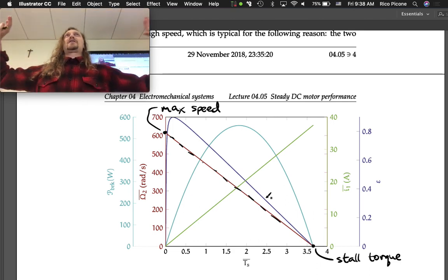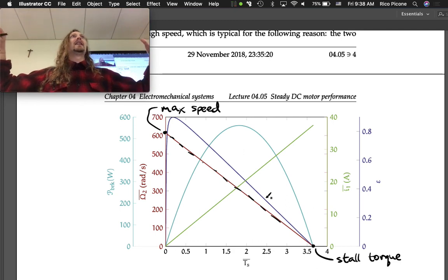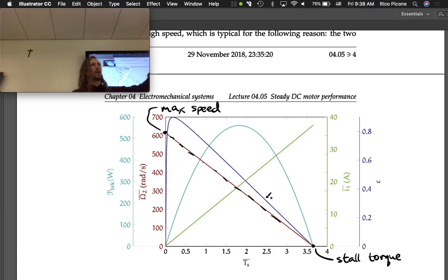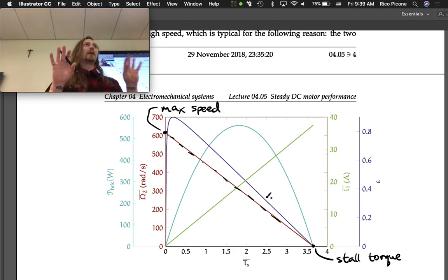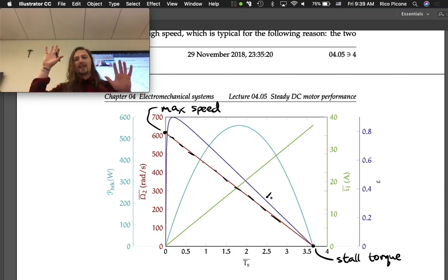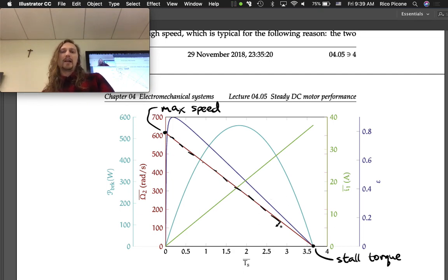So it's not a perfect analogy, but it actually is effectively the same phenomenon, because even in engines you have this torque-speed trade-off. Torque and speed are the two power flow variables and they multiply together to get power, so often your power is what you're trading off between torque and speed. Power doesn't say constant, but it is harder to get around. So torque and speed are sort of a trade-off. Okay, so that's the main motor curve.